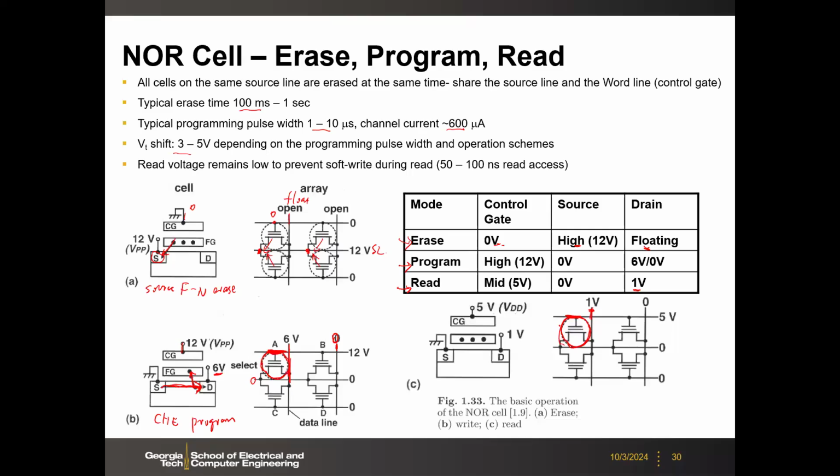So here, depending on the threshold voltage, you may read out the currents. If the cell is erased, then the threshold voltage may be very high. Then you won't read any current. The threshold voltage may be even higher than your 5 volt gate voltage. So the read is pretty fast actually in the NOR flash. It's like a regular transistor, and if you have 1 volt, you may pass like tens of microamps. Therefore, the read speed could be as fast as like 50 nanoseconds.